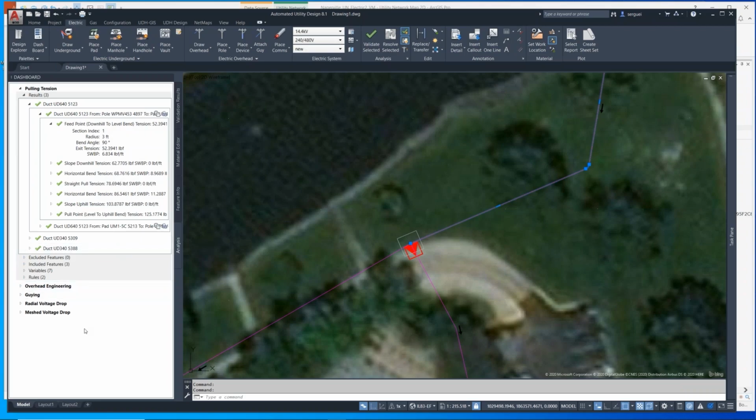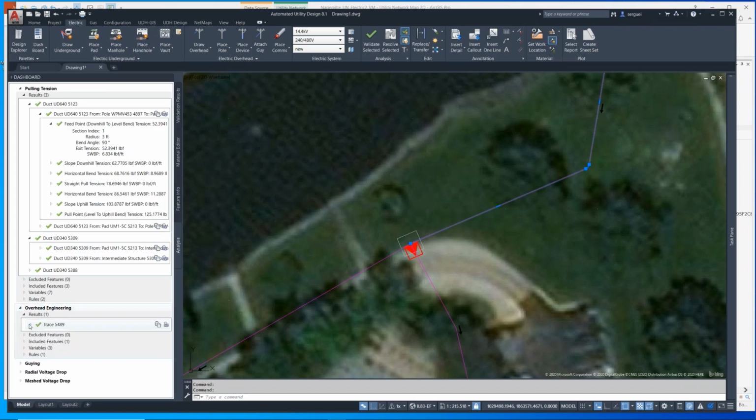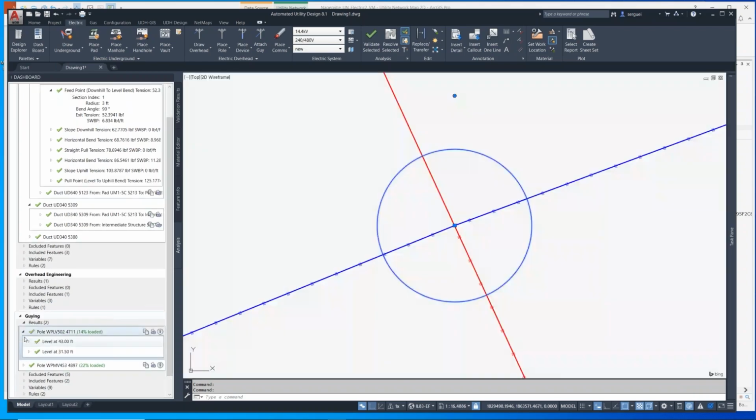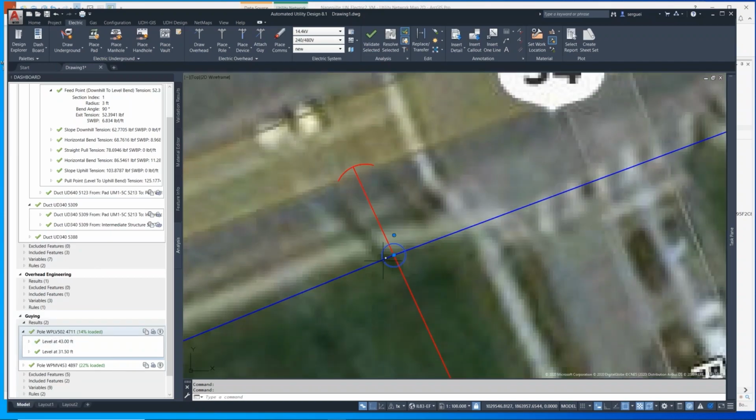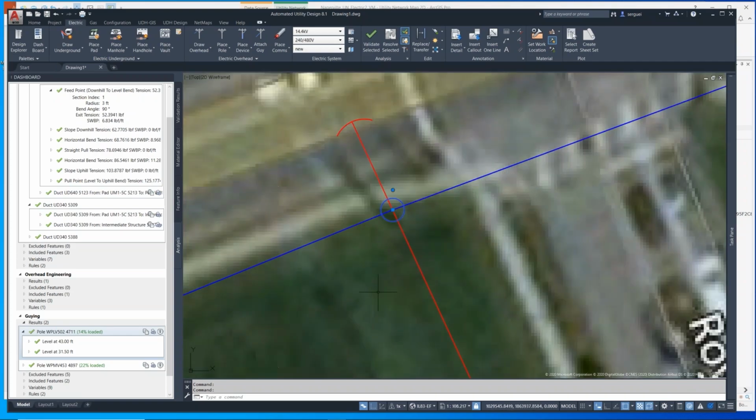In general, what we do with our calculations is for material choice and for the bulk of the situations that designers face. But if you're in downtown, some city, and you have 4 double circuit cross arm turn poles, buck arm turn poles, you're going to want to run that through an analysis tool. And there are multiple workflows that AUD can enable with Utility Data Hub analysis package, where we could send data out. You could draft it in AUD and send it out to OCalc or send it out to SPIDA-Calc and have them return back whether or not this will work.